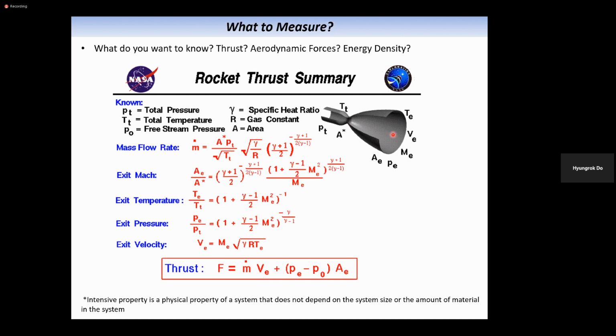If you put some pitot tubes to estimate the velocity here, maybe you will have a kind of rake having multiple pitot tubes along a line. That could be another way of measuring that, but because the temperature is extremely high in this case, your pitot tube will be easily damaged, and that will also disturb the flows in the downstream.